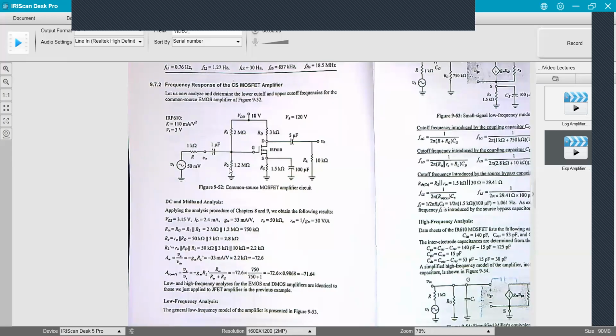They help conserve power by having very little current flowing through here, but I can still generate the voltage I need here. I can scale these. I can make this a 12 meg and a 20 meg ohm resistor, or I can make them 10 times as small, and you'll get more current. So the values of these were chosen so that the current that flows through here is minimal compared to the current that's flowing through here.